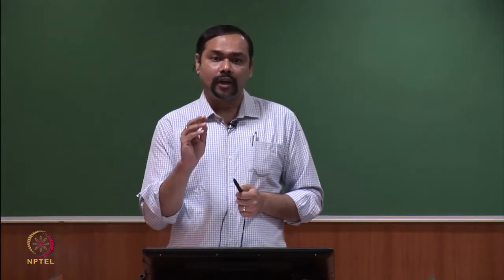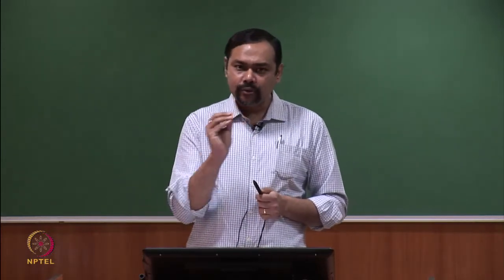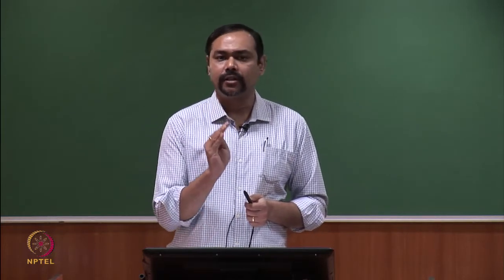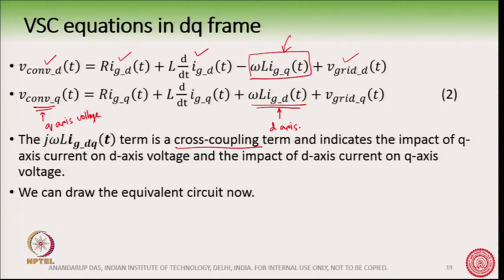So, we will do some tweaking in the controller by adding a feed forward term, by which we will try to nullify or minimize this cross coupling effect.